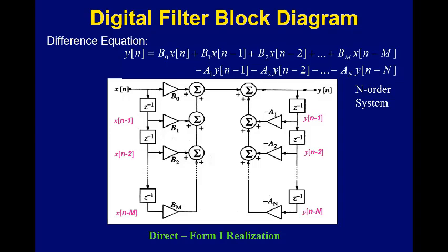of that. And this is one of actually several different implementation structures that can be used to make any digital filter. This happens to be one that's so closely tied to the difference equation, we call it a direct form. Called a direct form because every one of the coefficients, b1, b2, a1, show up in this diagram.